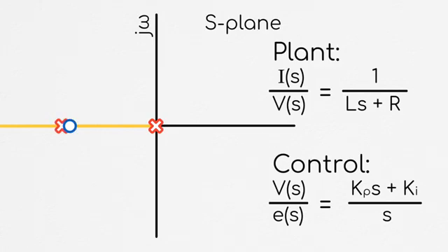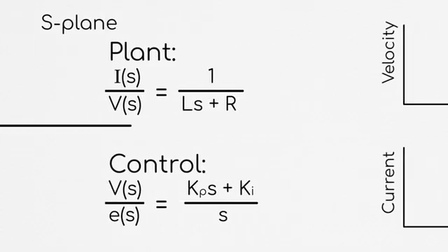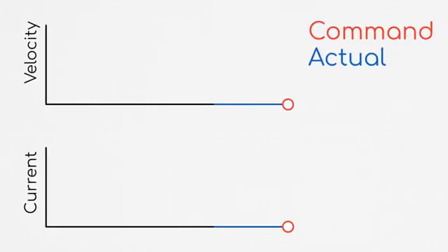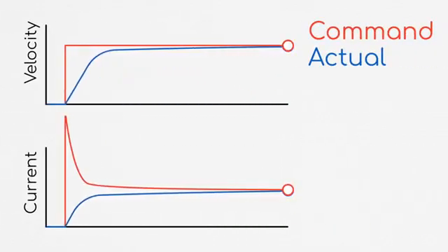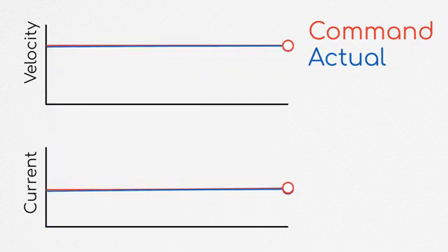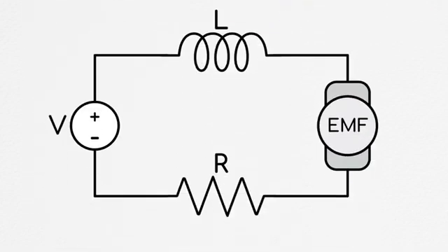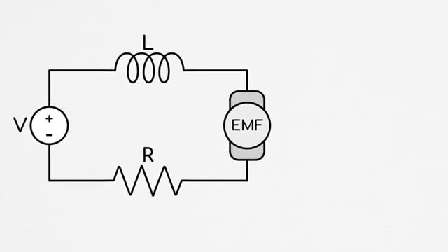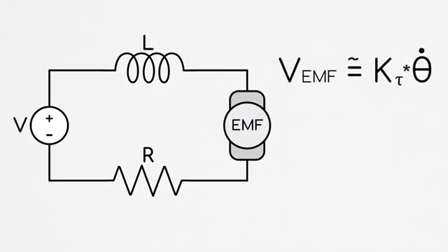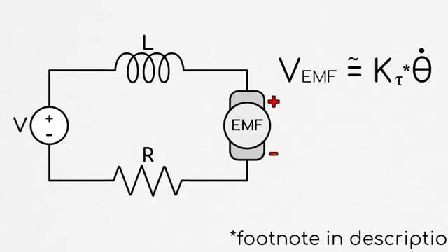This approach results in quick system responses with minimal dynamics, and if you're controlling for quasi-constant rotor velocities, this integral term will eliminate the issue of back EMF. However, if you're using a motor and a servo system where velocities aren't quasi-constant, we can still minimize this back EMF disturbance. We know from earlier episodes that back EMF is approximately the torque constant multiplied by the angular velocities, assuming you have your units in check. And it produces a voltage in the motor which resists the rotor's turning.